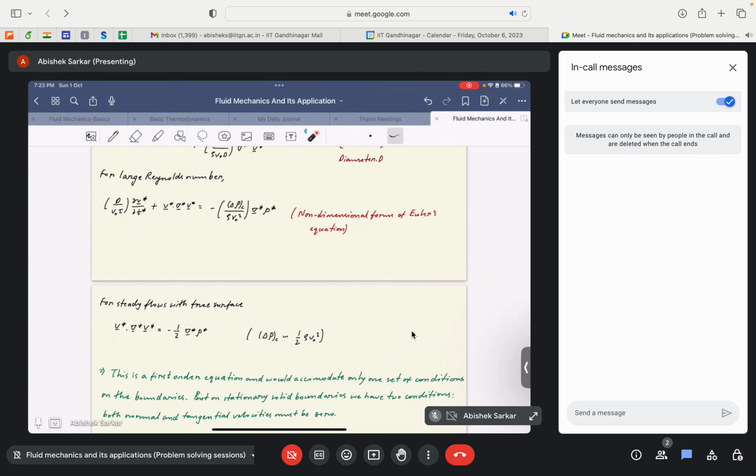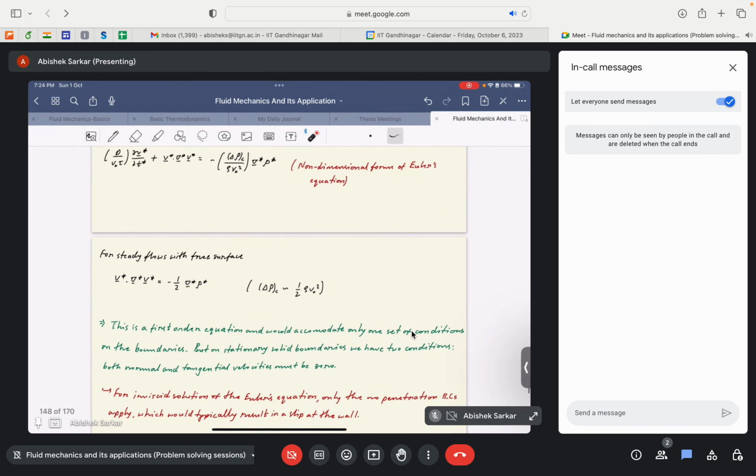The advective term, the unsteady term, or even the viscous terms have specific scaling factors that are uniform throughout the flow field. But pressure, since it's a very funny entity, actually scales with the factor that drives the flow. If the flow is governed by viscous effects, the pressure will scale as the viscous term, and if the flow is governed by its kinetic energy, then it will be scaled as the kinetic energy. And as I told, in the case of flow over a flat plate, and similarly over an airfoil, or for most inviscid flow domains, the flow is mainly governed by the kinetic energy. We can also think of it this way: since the viscous terms themselves are neglected, there is no point in scaling pressure with respect to the viscous term, right?